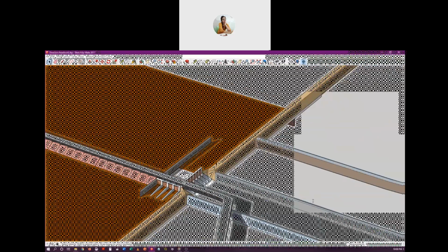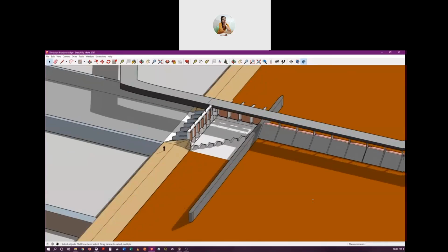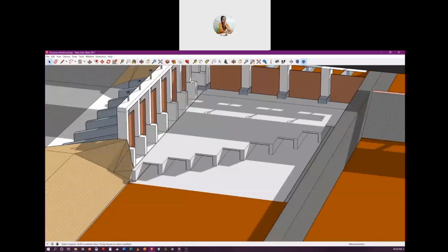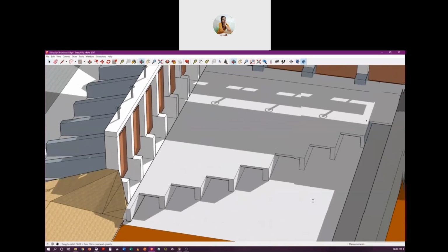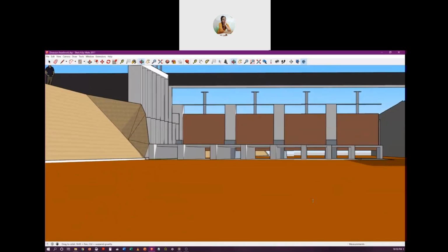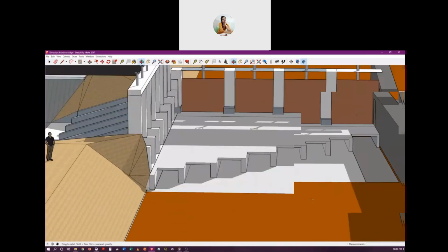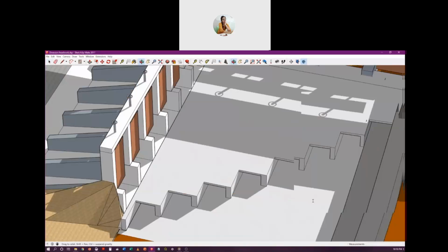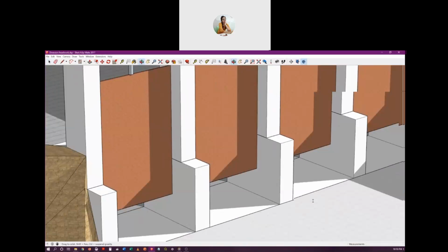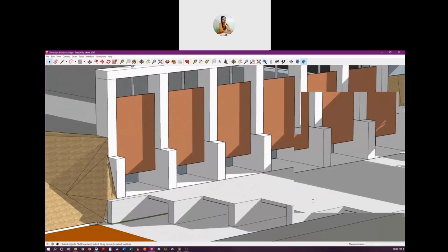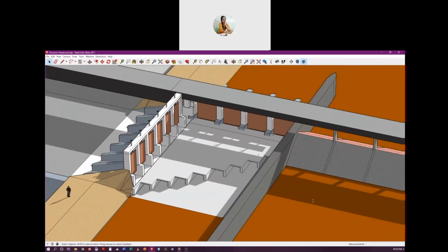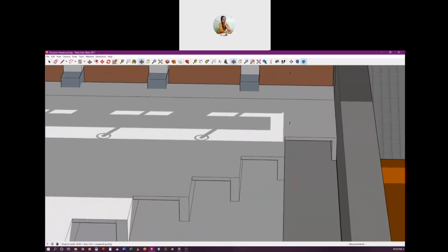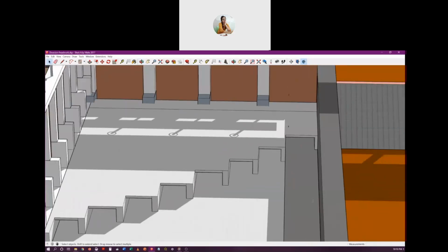Now, let's discuss some more about these undersluices, the silt excluders. They have a very peculiar arrangement. These are long tunnels. The tunnel very close to this head regulator, through which water is transferred to the canal, is the longest, and as we move away from that, these tunnels become shorter and shorter.